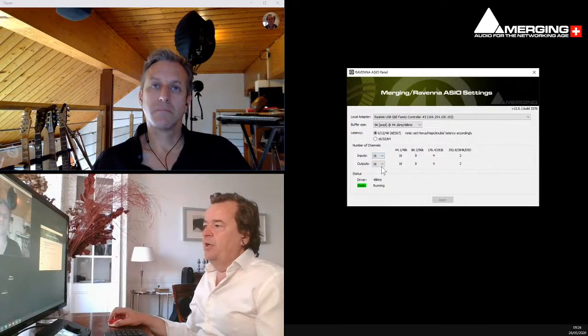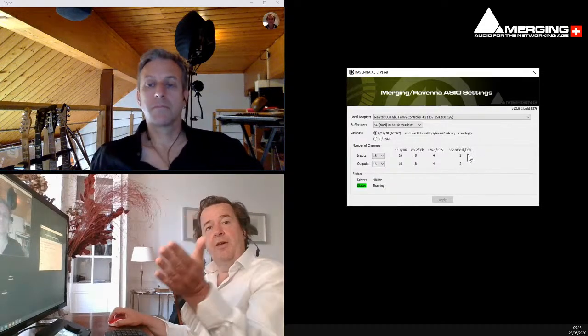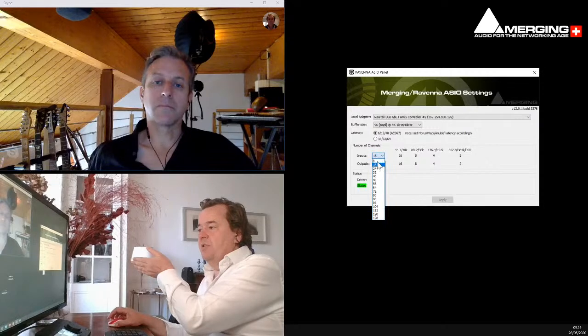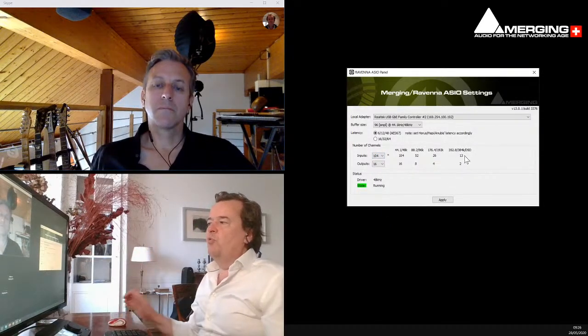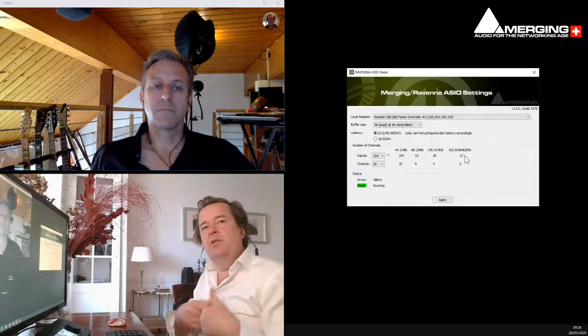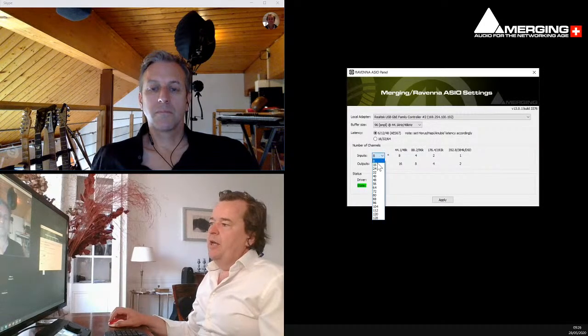And then here, these are the numbers of channels. So obviously I can go at one FS up to 128, each time by 8 channels, and the same thing for the outputs. And obviously you have here the indication of how this behaves when you go higher in sample rates. If I go now to 104, I will be able to record or input 13 DSD channels or PCM 8 times, so 384 kilohertz on that aspect.